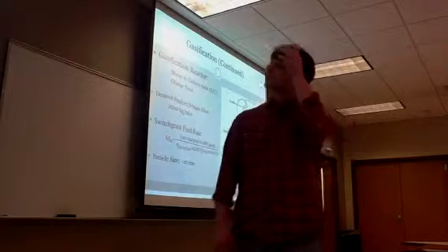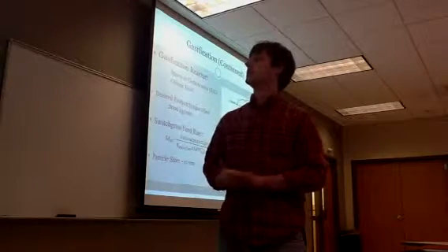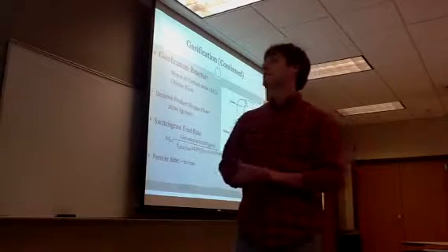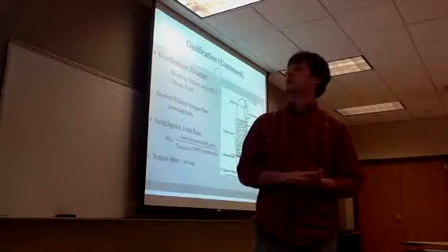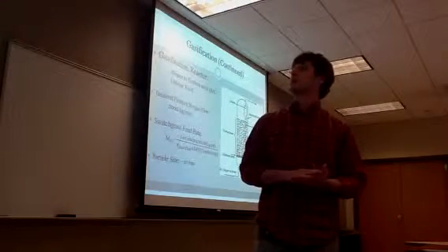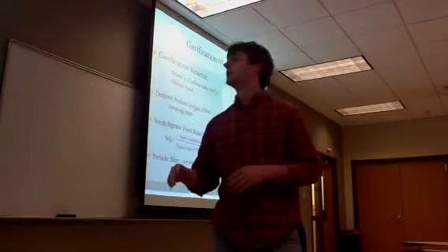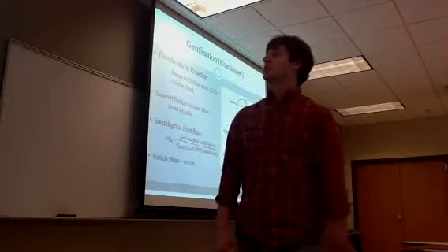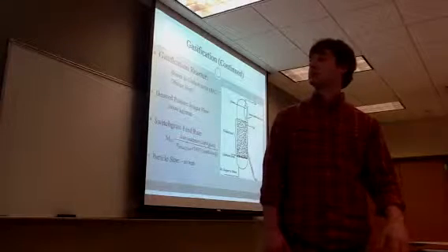Next, some properties of the gasifier reactor. Some design considerations: our steam to carbon ratio is very important, especially your steam flow rate relative to your carbon flow rate in the biomass content. And also your olivine feed is very important to provide the correct amount of heat, which is fed from the steam power generation combustor.